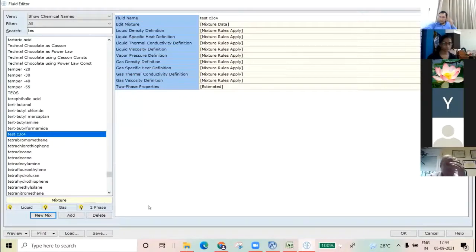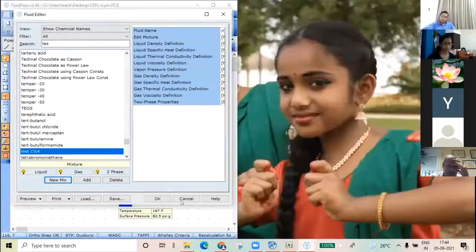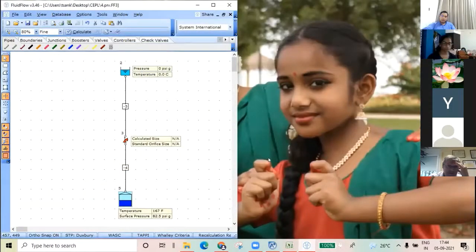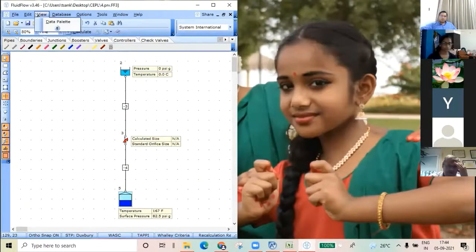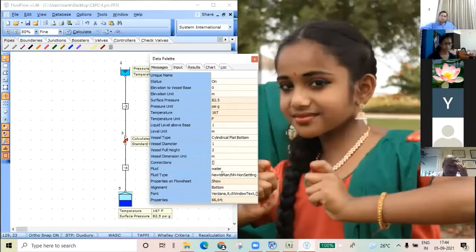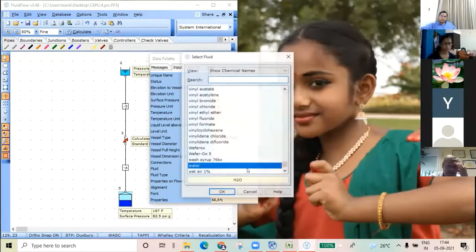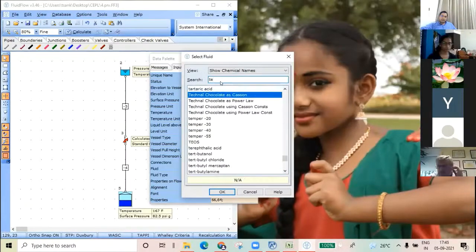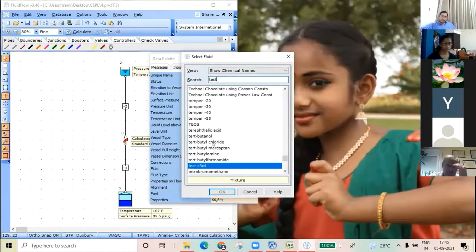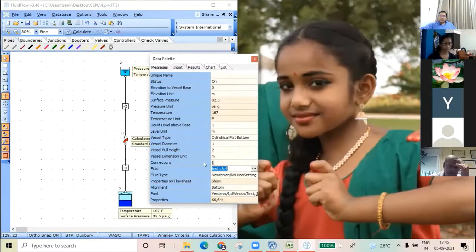Mr. Mark, is it done? Yeah, I think so. I think it's done. All right. You can click on that vessel, then change the fluid from water to test C3, C4. This one. Type T. Test. Yeah. Click OK. Now we can click calculate.